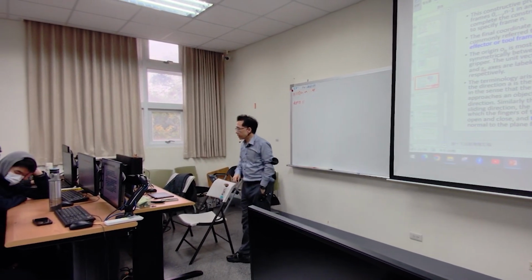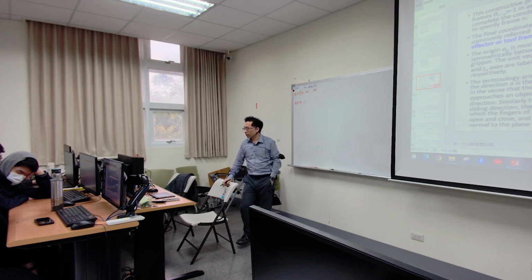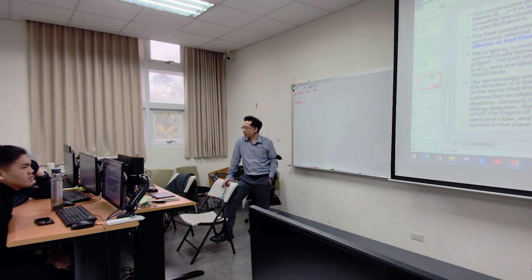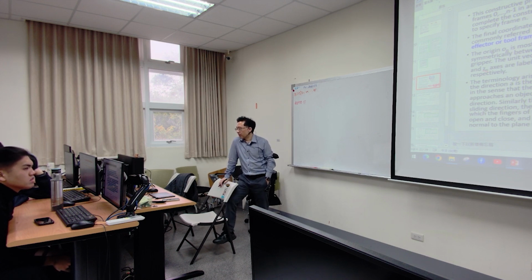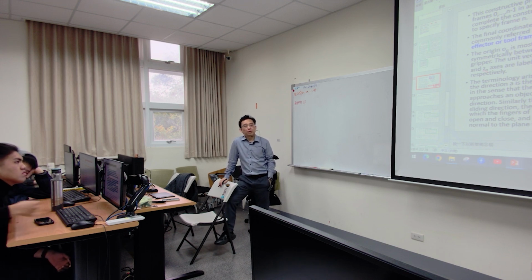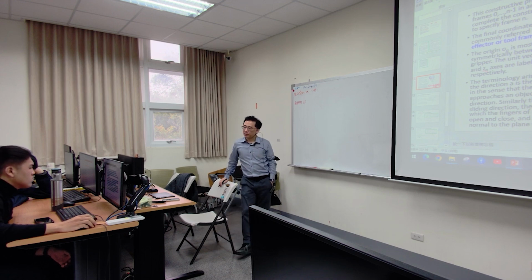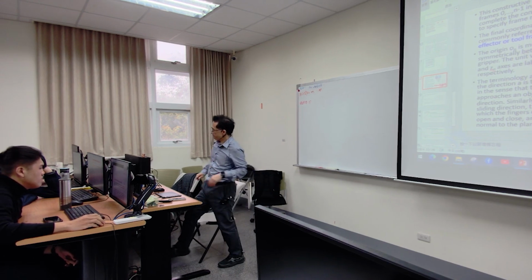So over here, it just mentions that if you want to know the position and orientation of your end-effector, just go ahead and multiply the matrices together. Then you can have the n vector, s vector, and a vector together, and also the position. So it's quite simple. Okay.